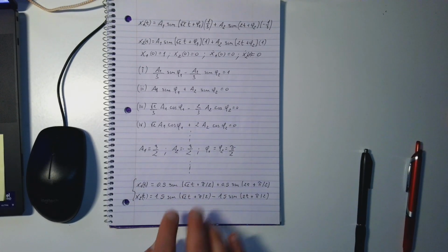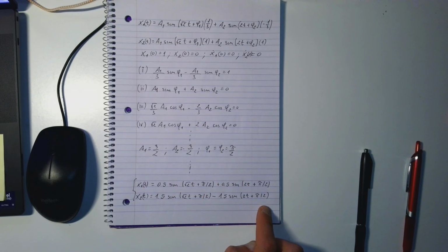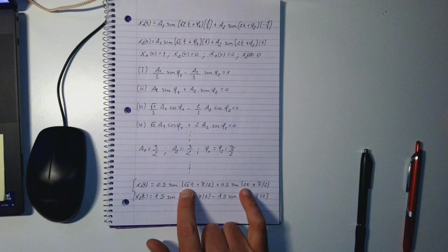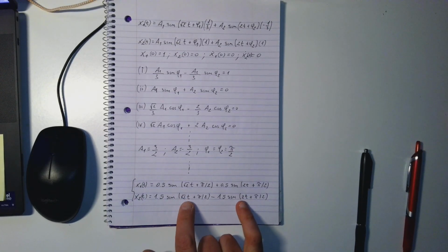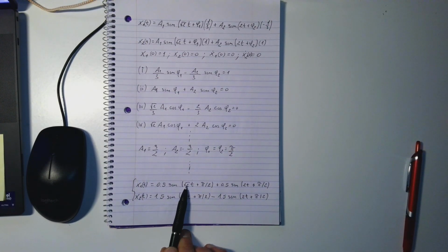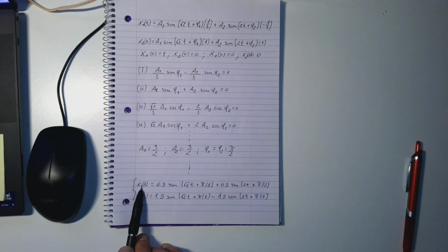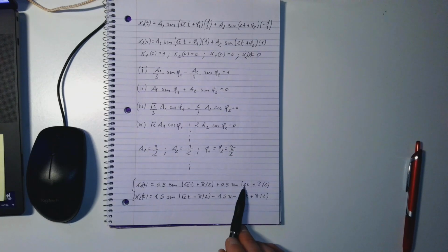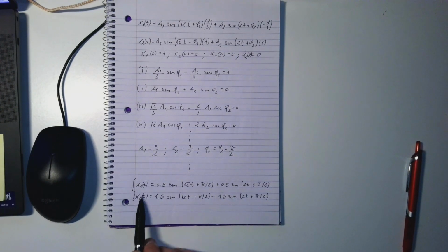We can see from this notation that we cannot isolate the two masses as a simple combination of two 1 degree of freedom systems, but there is some coupling. It means that both frequencies influence both masses, because as you can see, this square root of 2 shows up both in the first displacement and in the second displacement. Same thing for this 2, which was the second natural frequency, it shows up here and here as well.